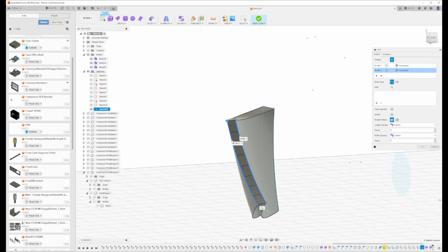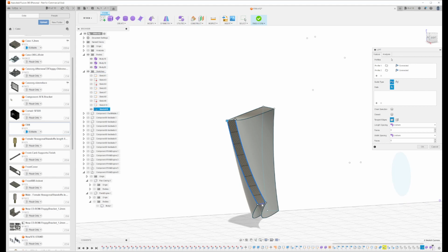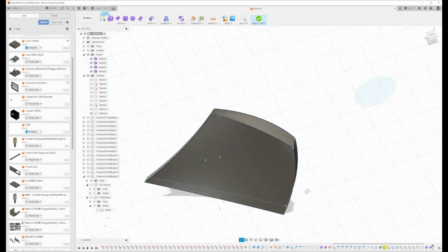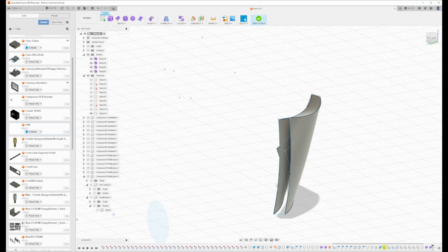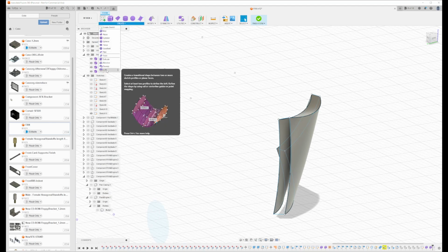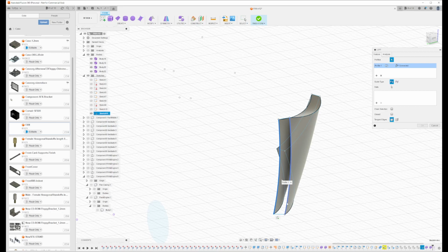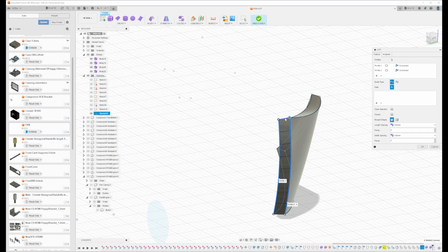What loft does is make a surface from one point to a different point. And you select anchor points, anchor lines, that it will conform the rotation after. And then again, loft. I am on the free version of Fusion, so if anyone wonders why I'm not using the paid function, it's because it's not paid. There. 1, 1.